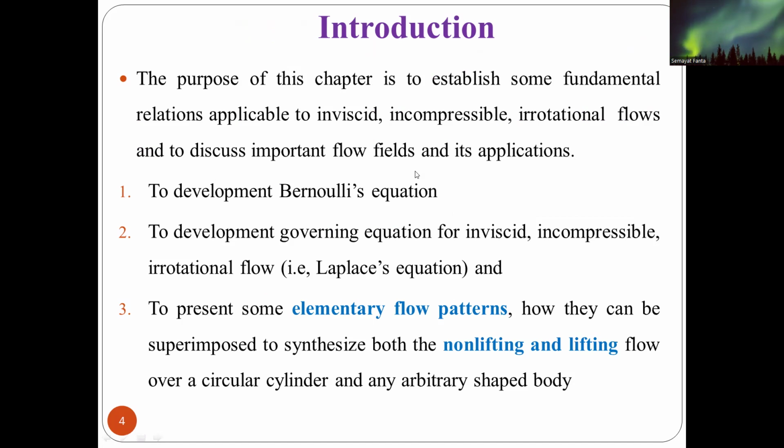So mainly we emphasize the development of Bernoulli's equation, the development of the governing equations for inviscid incompressible irrotational flows like the Laplace equation for the velocity potential as well as for the stream function, and to present some elementary flow patterns, as I have said, and how they can be superimposed to synthesize both the non-lifting and lifting flow over cylindrical shapes, circular cylinders, and arbitrary shapes like airfoils also.